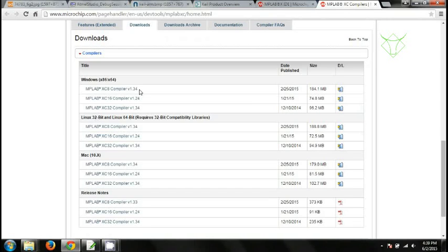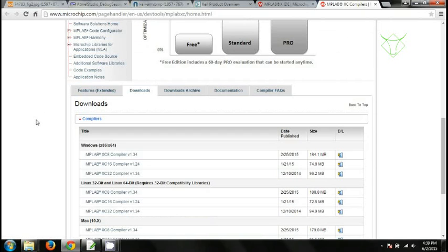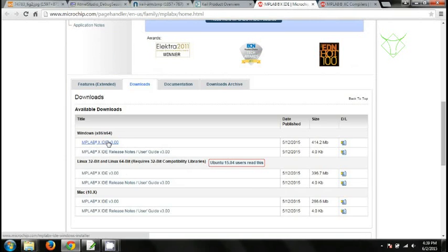So if you see here, Microchip has different compilers for different architectures. XC8 is for 8-bit architecture, that is PIC16, PIC18, PIC10, 12, all those things, and XC16 is for PIC24, PIC30 series, 33 series. And obviously XC32 is for 32-bit architecture, that is the PIC32MX series. Okay, so we are concentrating on the XC8 compiler and MPLAB. It could be the MPLAB X IDE or the MPLAB 8 IDE. This X is basically 10, MPLAB 10.